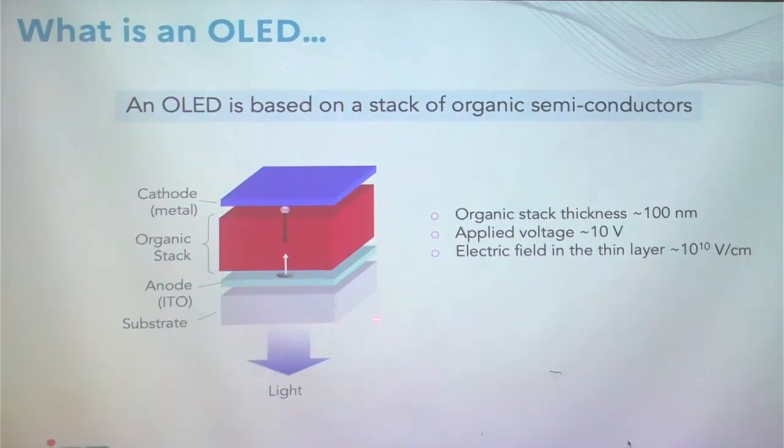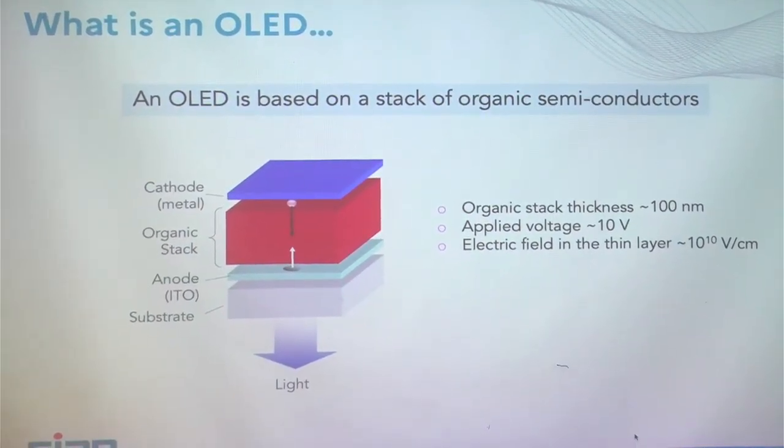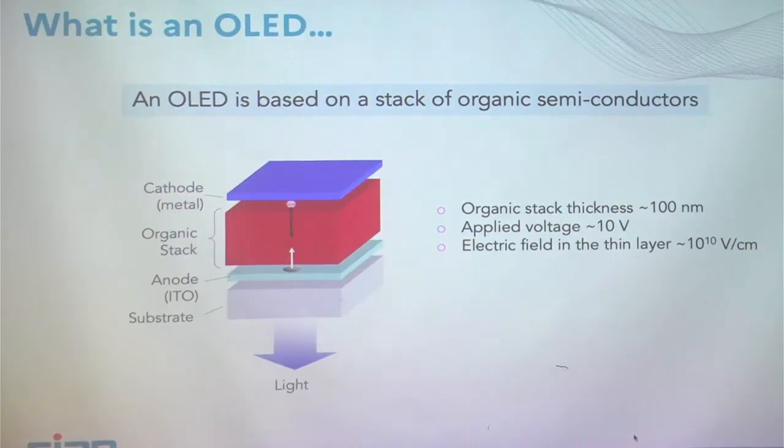There is the way that they work. You have a substrate that can be a thin piece of glass, or can be a plastic, PET, or plexiglass, or can be even metal, what you want, or even tissue. You have different options. Then you have an anode made of indium tin oxide, and then on the top an organic stack that creates the PN junction. I will show you how. And on the top you have a second electrode in order to create the electrical contacts.